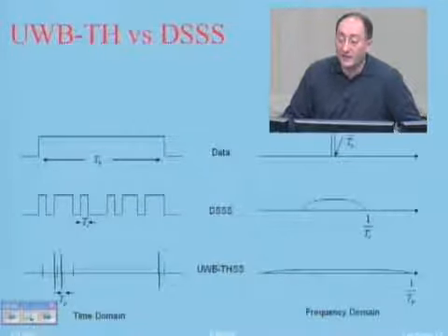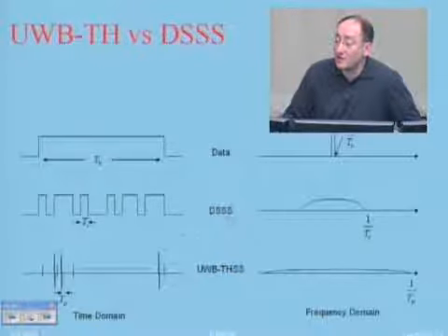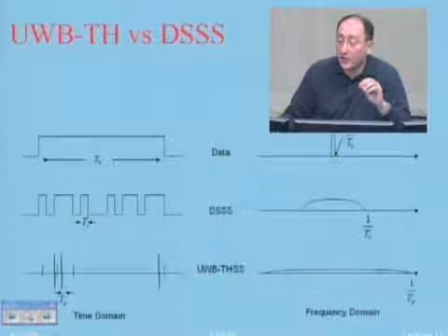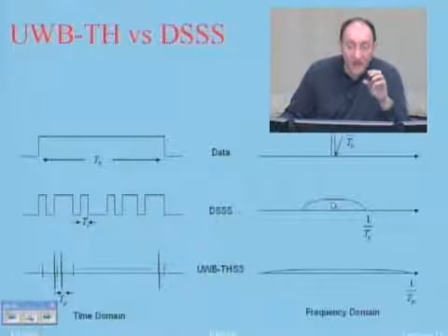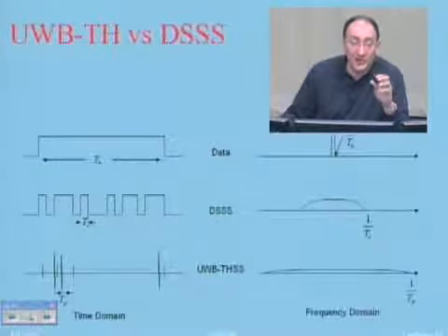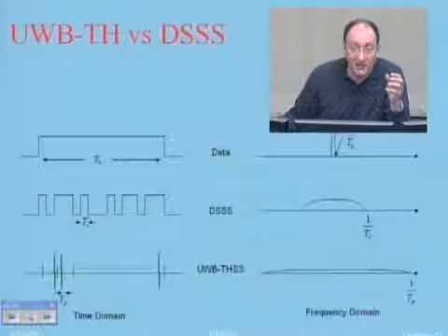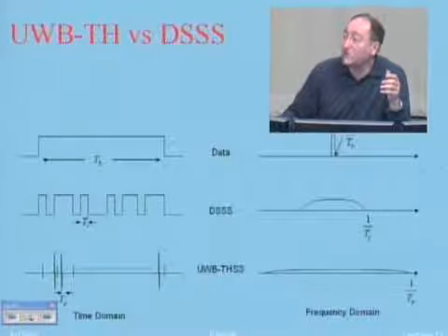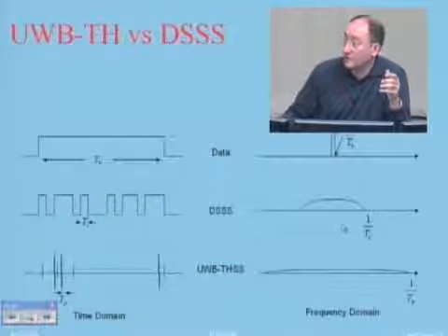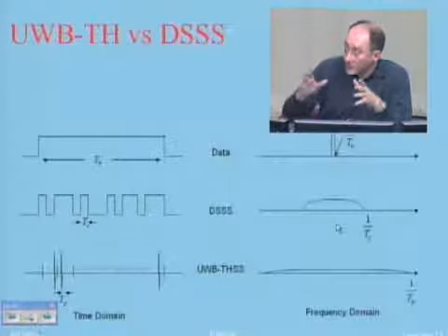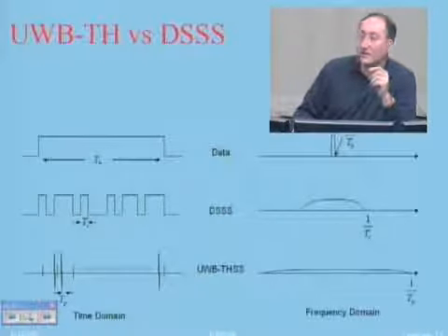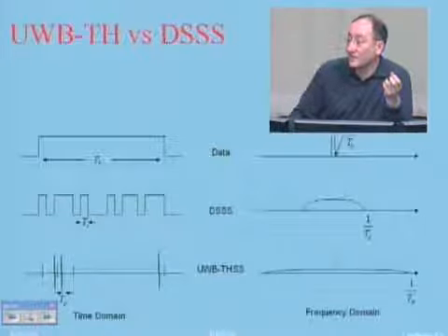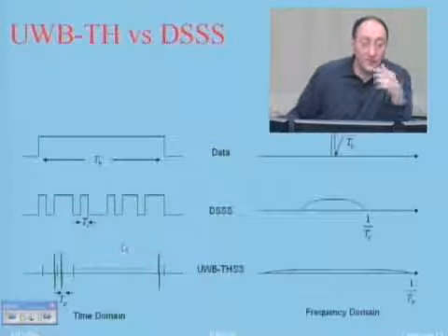You remember that one of the advantages of direct sequence spread spectrum was that in this type of communication, your power spectral density is low, comes around the noise. So nobody realizes that you are communicating. While if you have frequency hopping spread spectrum, people can put a scope and see that, yes, you are communicating. So that's the advantage of it. This one is even better than that, for interception.